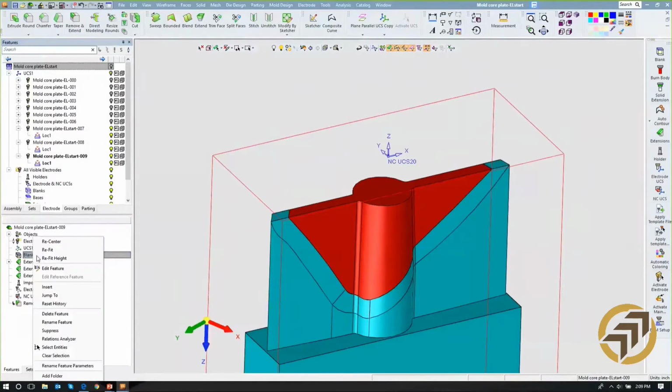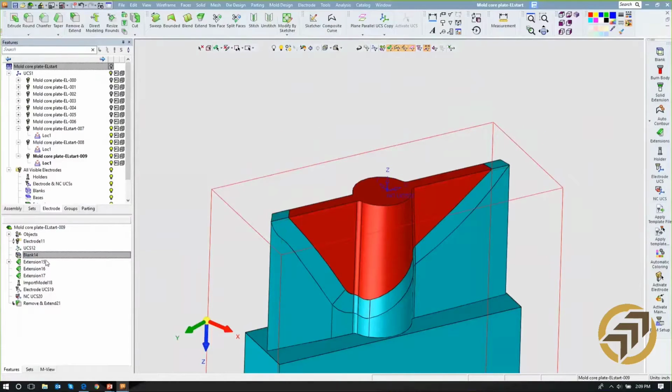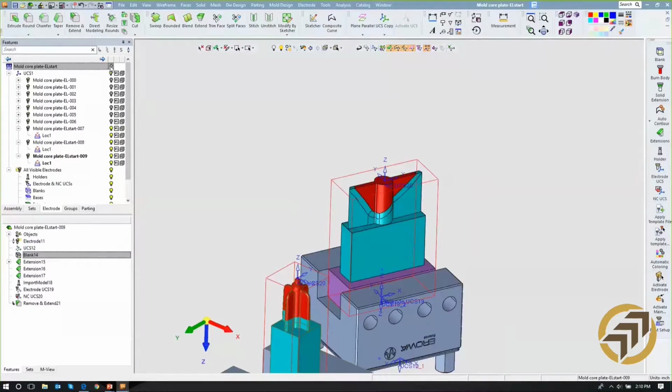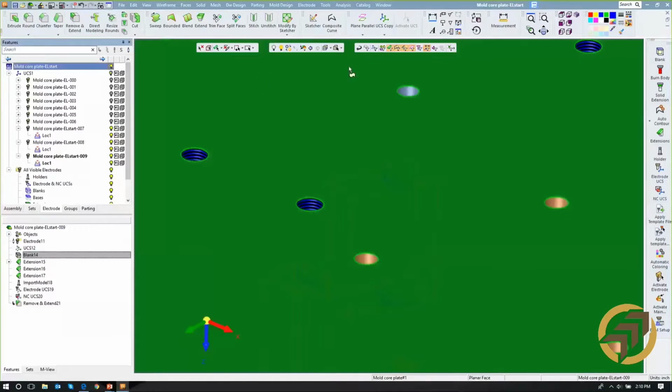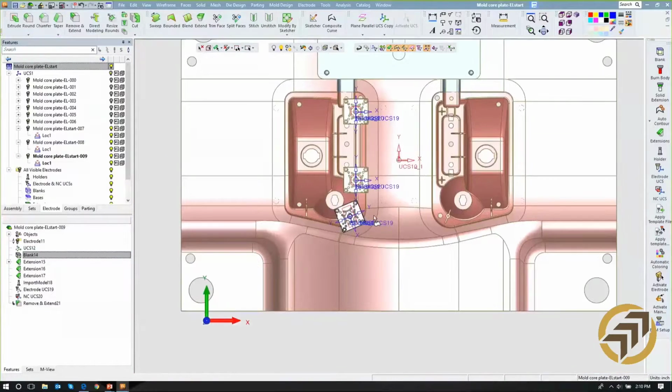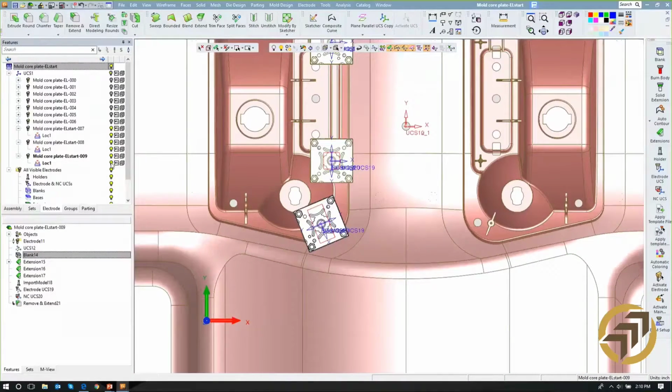One nice feature is those refits are always accessible. So if I've made a change, I can step right back over and say, let's just refit the height. So now it's reduced down, and the graphite I order will be graphite I use. I won't be cutting stuff off to waste it. Well, that means that little feature left behind is going to need its own electrode. So let's flip that back around, and we'll take a look at that one then.